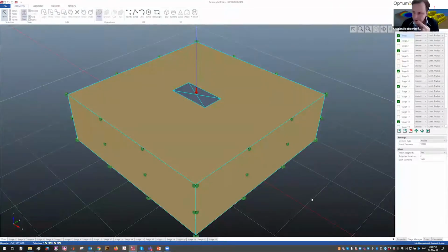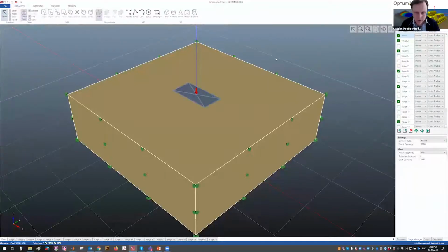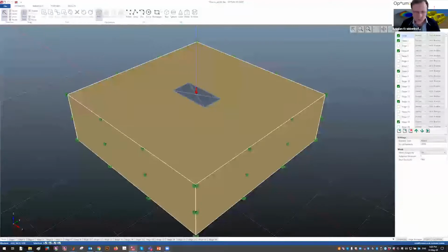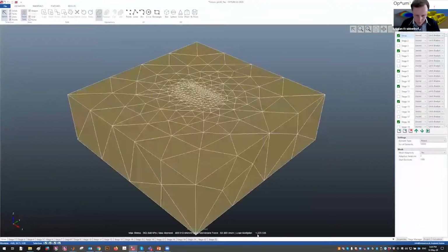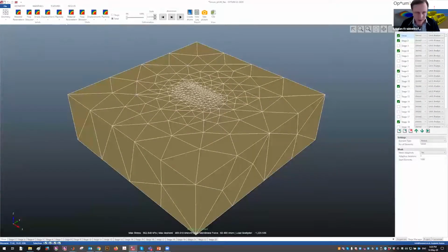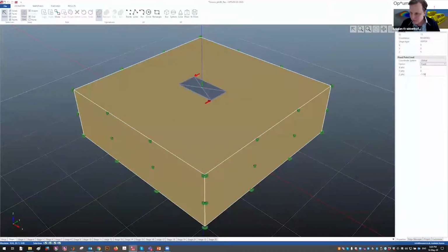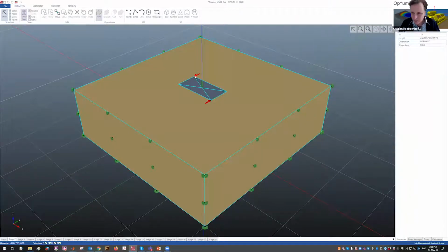This is a footing that is 4 by 2 meters, I think. So you do a standard limit analysis for vertical capacity, and then you start generating the other points on the VH diagram. In this case, the vertical capacity was 1220, so you apply a vertical force that's a little less, 1156 in this case, and then the red forces here are the forces that generate the torsional moment.